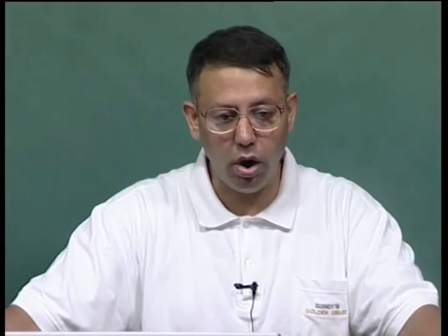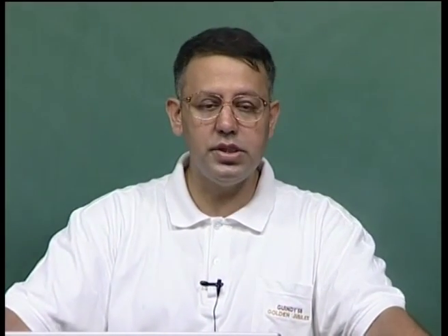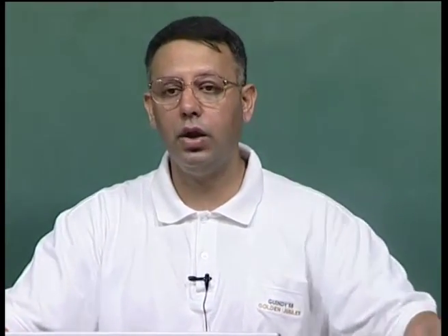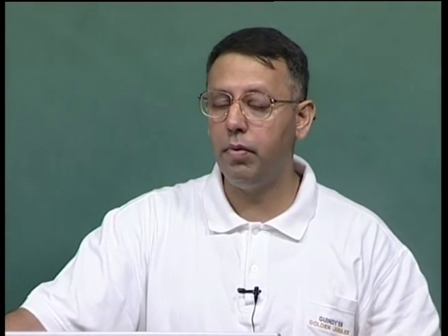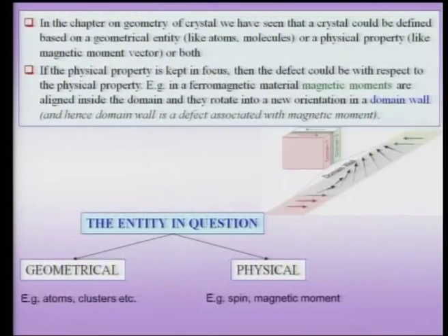and you would notice that once the vacancies have got ordered and they have a sublattice, I can now even talk about a hierarchy of defects. In other words, first of all, I have a vacancy which has got ordered. Now, I have a sublattice for the vacancies. Now, there can be a vacancy in the vacancy sublattice which would actually be an atom. So, I can now talk about a hierarchy of these kinds of defects, but I need to remember that once the vacancies have got ordered, they have a profound influence not only on the crystal structure but therefore also on the behavior of the material.